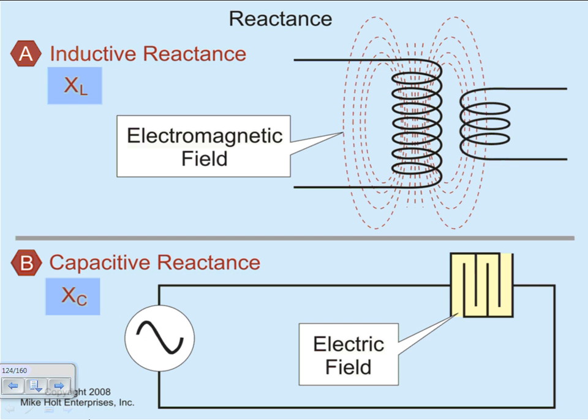So how are you going to solve the problem and make Excel Energy happy? You add a capacitor correction. So what do you do when you add a capacitor, guys? When you add a capacitor, you basically raise your power factor. So Excel is giving you 100 amps and you're using 100 amps because there's no losses in your system. So how do you correct the power factor from 70% to 100%? You add a bank of capacitors right at the service. By adding them, you shift the power factor up. We're going to talk about this one in the power factor chapter. Now you are paying for 100 amps and getting 100 amps, and everybody's happy.